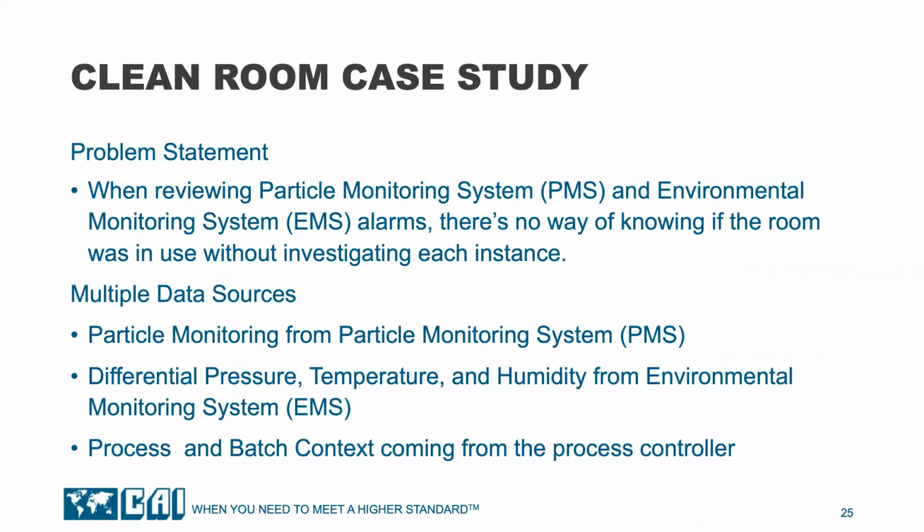This is a case study that has as its basis a real-world example that occurred while I was working for a biotech facility a few years back. During a corporate audit, the auditor requested to see the differential pressure, the DP alarms, for our clean rooms. I'm no expert on clean rooms, but what I've taken from a few experiences is that pressure needs to be higher in a clean room than the surrounding rooms so that when an entryway or exitway is opened in the clean room, no bad stuff gets sucked in.